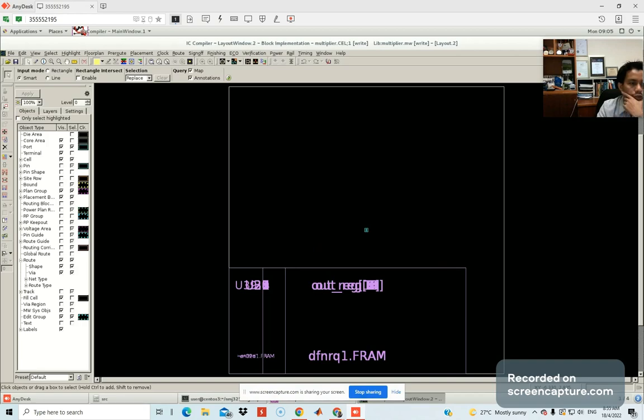We will define the power rail. When we perform that, that task will actually eliminate the errors. We will do the power rail, we create a floor plan. Remember the lecture on floor plan we have discussed in class, and then we add power rings. Then next I think we do place and route and optimization, and finally we will get the layout. We will do it step by step as we go along in this lab demonstration, recorded video demonstration. So we have already opened our design, and what's to do next?